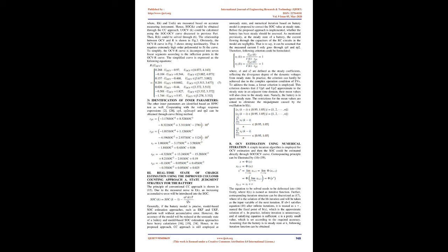The relationship between OCV and R is shown in Fig. 3. Obviously, the OCV-R curve in Fig. 3 shows strong nonlinearity. Thus it requires an extremely high-order polynomial to fit the curve. To simplify, the OCV-R curve is decomposed into 7 linear segments according to the inflection points in the OCV-R curve. The simplified curve is expressed as the following equations.